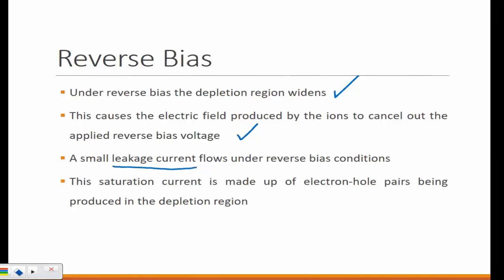This is the drawback of semiconductors, and in any application you take, even with technology nowadays, there is always going to be some leakage current even when you are operating under reverse bias. That means you are consuming power from the battery or the source you are supplying. That's not going to be an efficient system if you're consuming power even when the device is not operating, right?